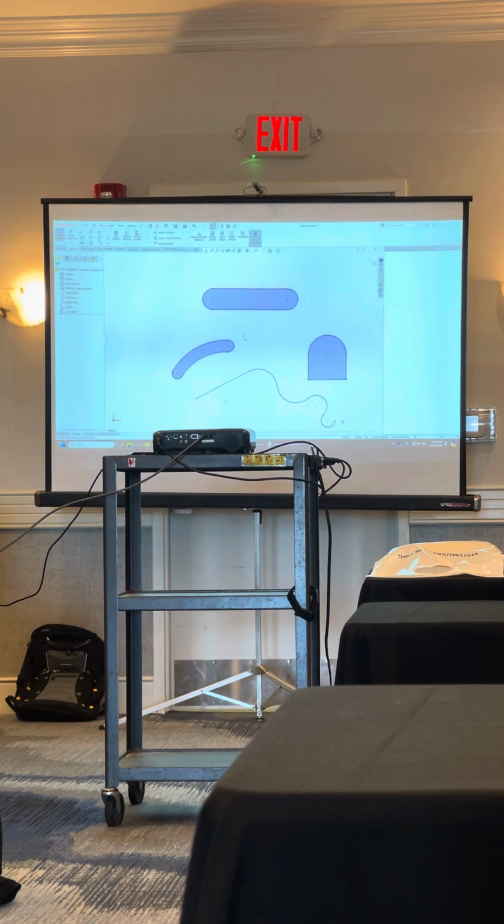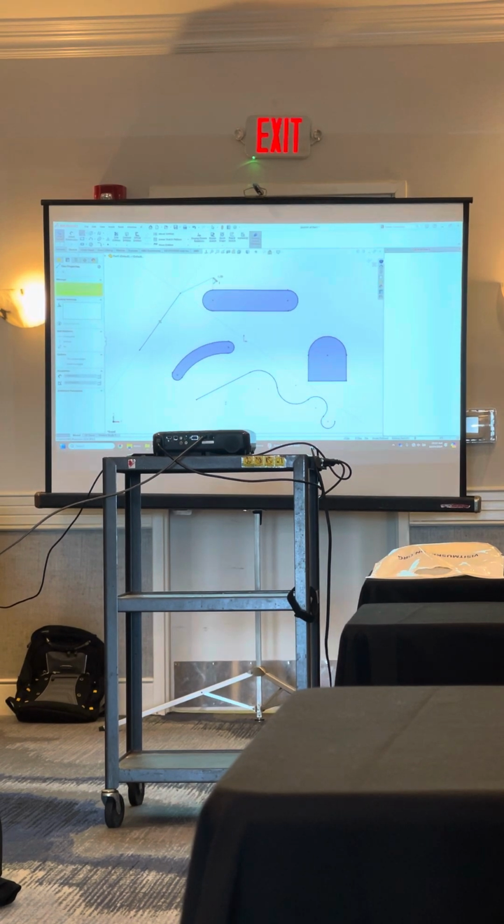Oh, good, okay. All right, so the other thing is if you inadvertently cause an arc to come out, you can hit the A key to cancel that once you move your mouse a little bit. So again, don't hit escape, go back to the command, all that good stuff.